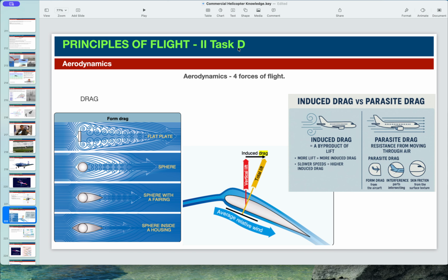You notice that there's far less rivets on airplanes. Howard Hughes was the first to kind of smooth out the airframe to make things nice and smooth to reduce parasite drag. Those early biplanes had an immense amount of parasite drag, and they were far from efficient in comparison to modern airplanes, which are really smooth and clean.